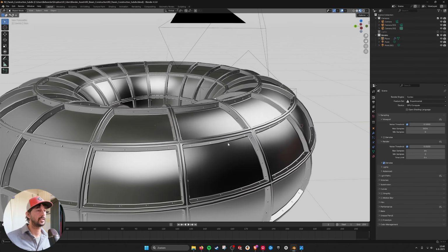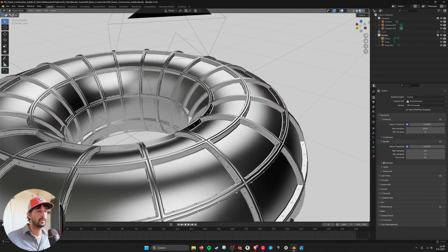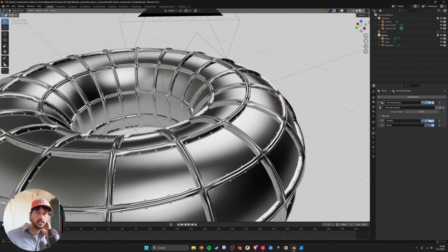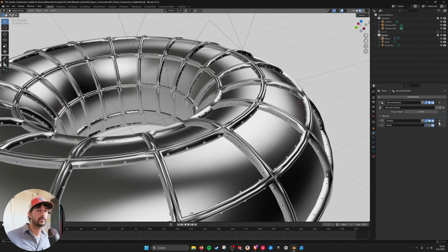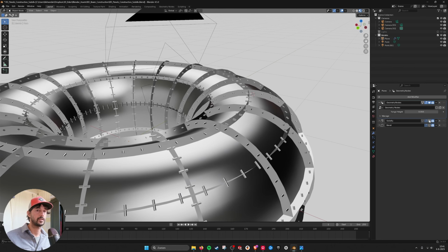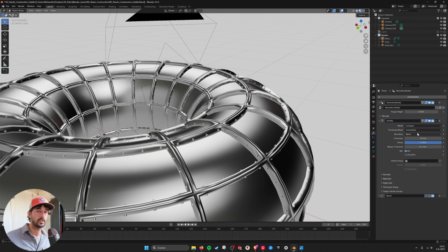And that's slightly different. And here you see I'm using a solidify and a bevel, and when I take these one off, you see that I only have these flat edges. And it's nice because the solidify has these more complex ways of extruding, so everything has the same thickness, which is why I use this.